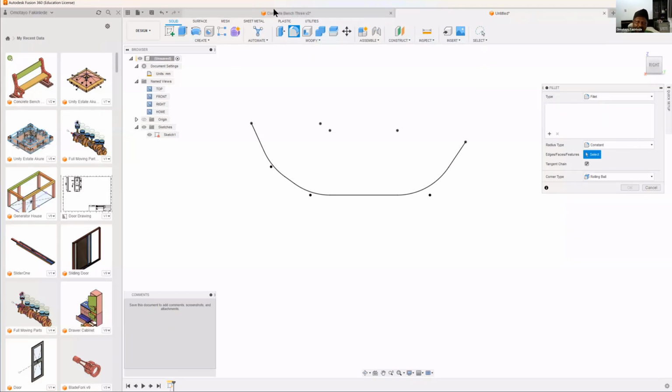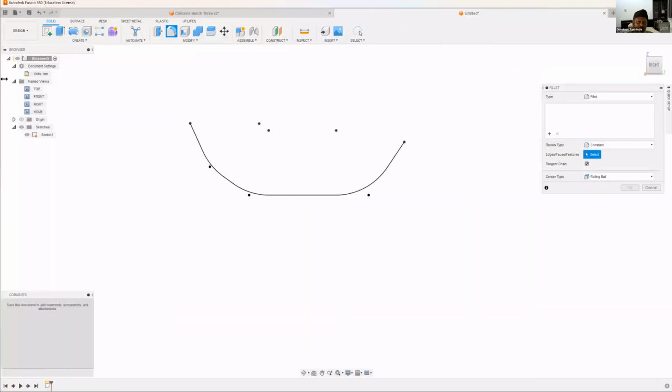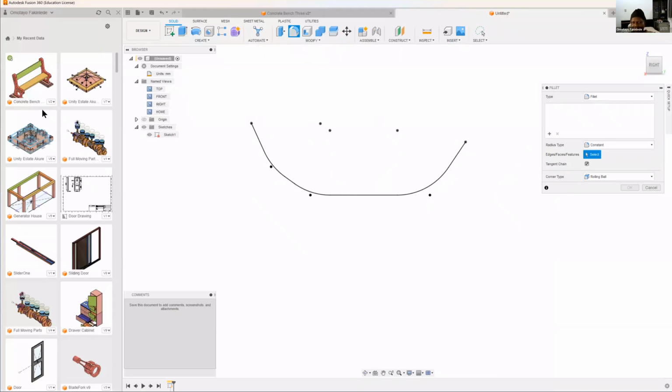Let us first do some demonstrations. For instance, the data panel can be toggled. This data panel here, if I want to switch it off, I click this once. It goes, the data panel is gone. If I want the data panel back, I go to that first icon on the applications bar, click it again, and the data panel comes back on.